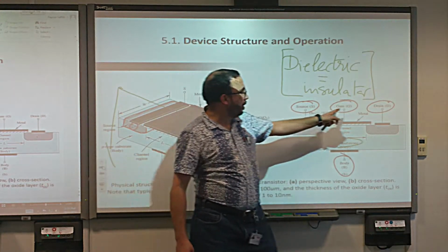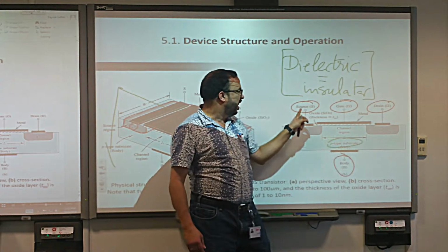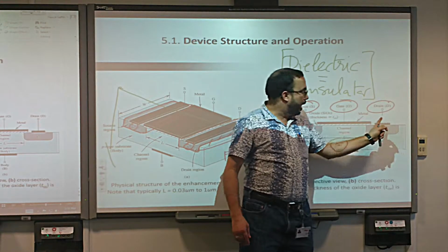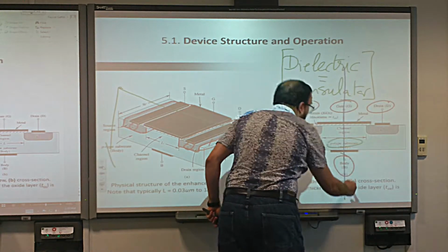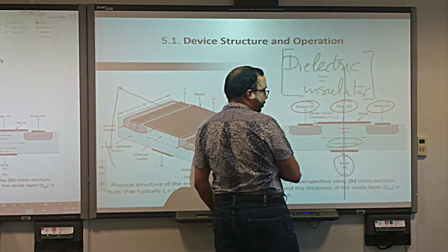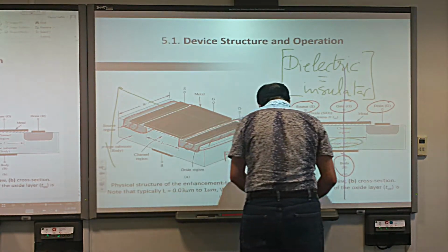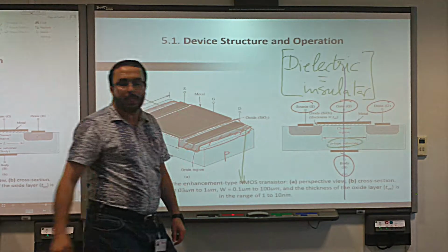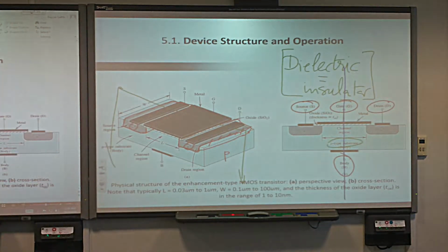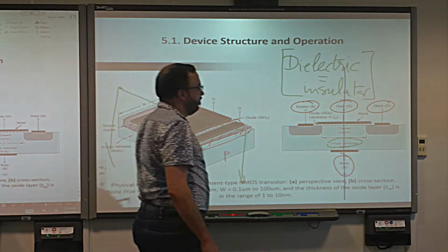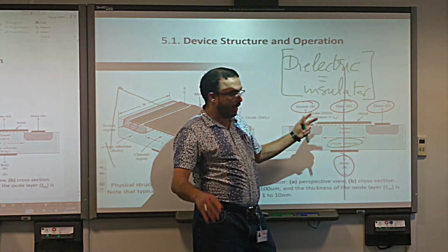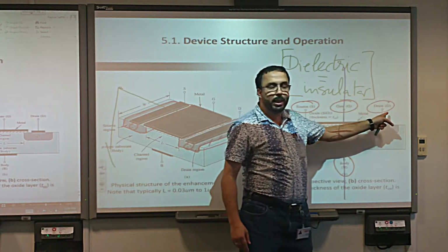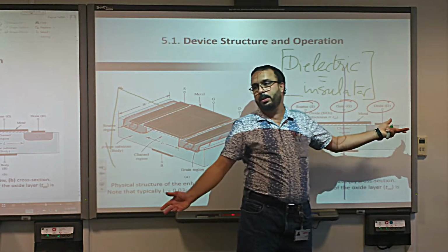So we have these 3 terminals. Now, if you can see physically, the source and the drain, they are symmetrical, yes or no? Like if you look here, across this line, don't you see that this is the mirror of this? Yes. Very good. So, physically speaking, it's a symmetrical device. As you can see later, the BJT is not symmetrical. Okay. Now, that means that without connecting anything, the source can be the drain, the drain can be the source. Yes or no? Yes. Symmetrical.